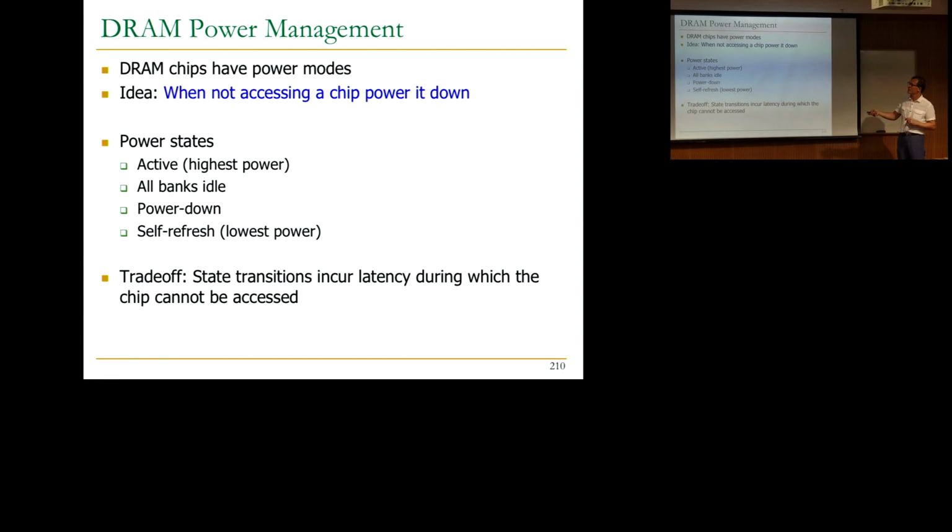And the granularity of the management is also important. Do you do it at the bank level? Do you do it at an even coarser granularity? As your granularity reduces, your memory controller complexity also increases, as you might imagine. We're not going to talk about this a lot, but keep that in mind. That's also important. That's going to exacerbate the difficulty of DRAM control, only exacerbate it.